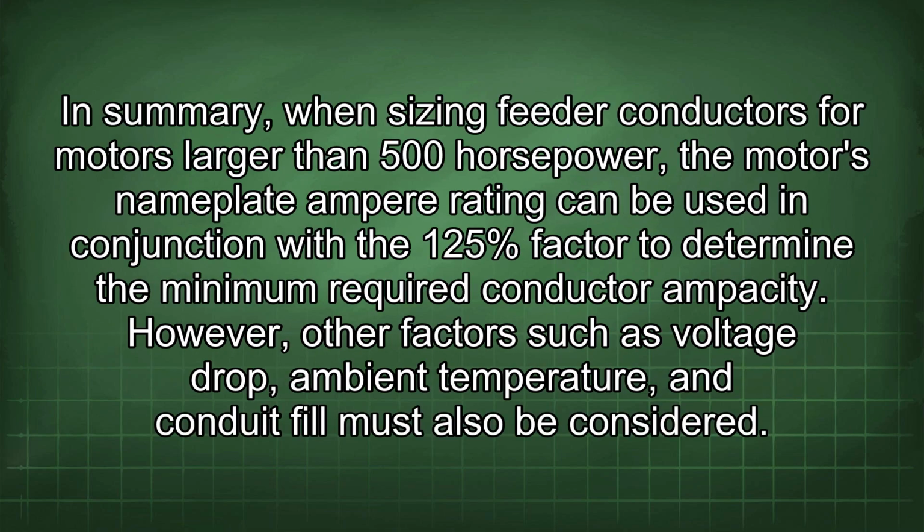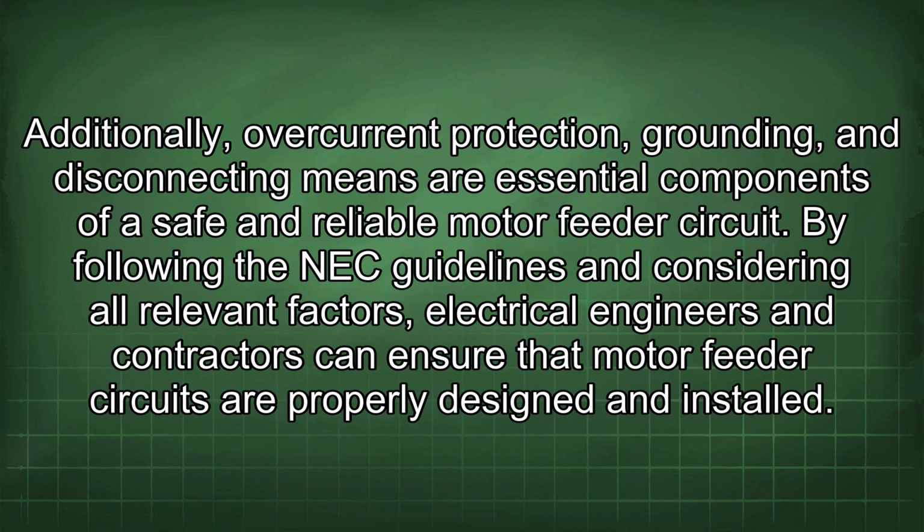In summary, when sizing feeder conductors for motors larger than 500 horsepower, the motor's nameplate ampere rating can be used in conjunction with the 125% factor to determine the minimum required conductor ampacity. However, other factors such as voltage drop, ambient temperature, and conduit fill must also be considered. Additionally, overcurrent protection, grounding, and disconnecting means are essential components of a safe and reliable motor feeder circuit.